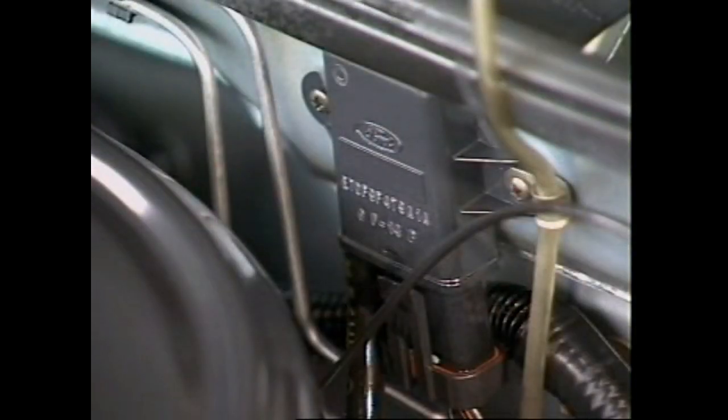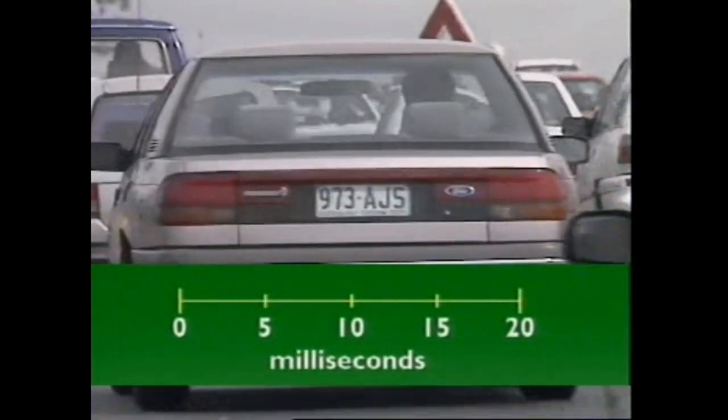As in a multi-point system, air entering the engine must be measured. This, together with the engine speed signal, provides the ECU with the basic information needed to determine the pulse width of the injector.